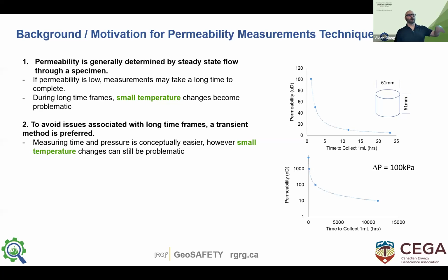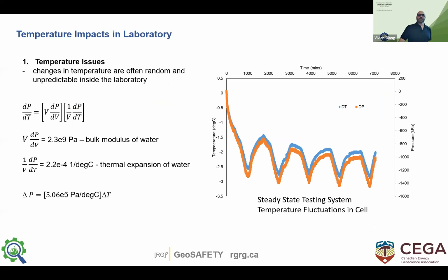A transient or a change in temperature in your system environment can impact your test. So a simple recommendation for anybody doing any sort of laboratory testing is to put a temperature probe in your laboratory, attach that to your data logger, monitor the temperature of your test, and include that in your experimental results.